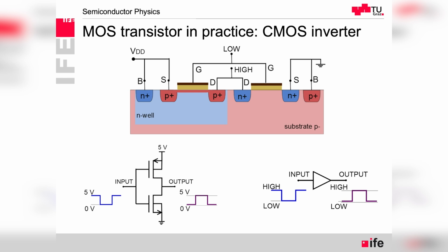It's actually a very similar concept and similar considerations to what we use in the sample and hold stage, where we sample a signal and then have it stored on the capacitor, not just to read out the capacitor value at any point later as is done in DRAM, but as soon as the following analog to digital converter is available, and it takes finite time to read the value, it converts the stored charge on the capacitor, the storage voltage, to a digital value, so that we can then consider it for data processing.